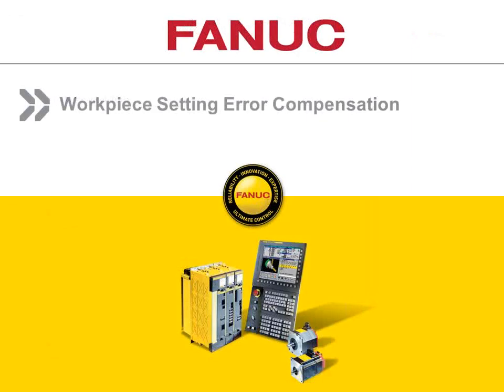So the first thing we want to talk about, and again, this is just a sequence of events in a program, is Workpiece Setting Error Compensation, because with that, we're telling the control where the part is located. I'm an old machine operator, and with 5-axis, at some point you have to get a hold of the part. You have to have some sort of work holding where you can clamp onto the part. This isn't like a 3-axis machine where you're going to throw this part up in a vise, because you're going to run into interference zones.